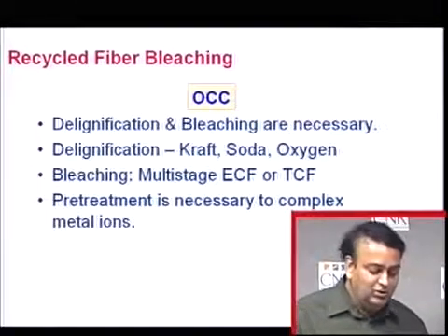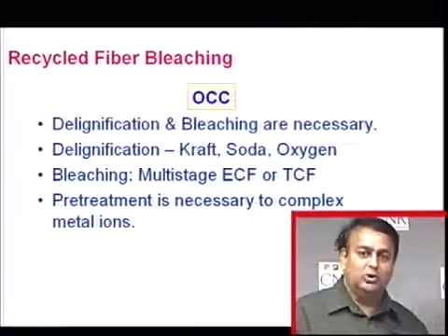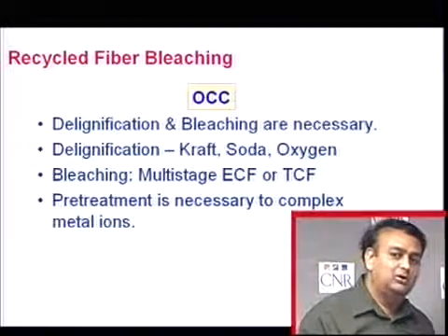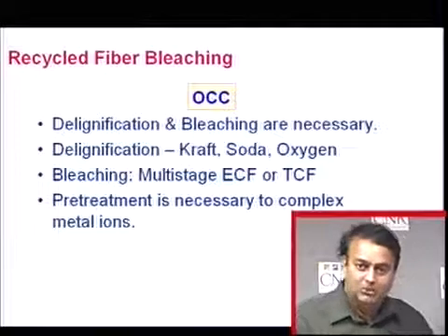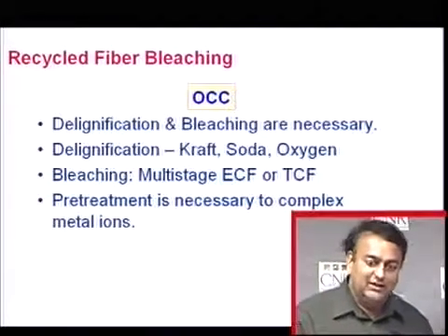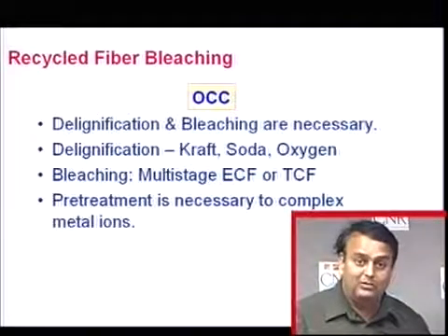Then you can bleach with a multi-stage elemental chlorine free bleaching or total chlorine free bleaching. Chlorine dioxide, peroxide, oxygen, and ozone can be used to bleach these fibers. Again, OCC contains a lot of metal ions. Pre-treatment is absolutely necessary to complex the metal ions.